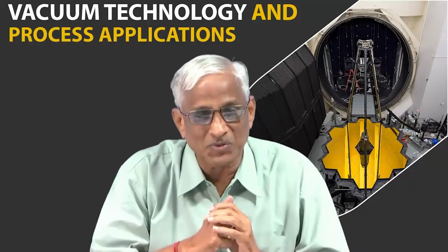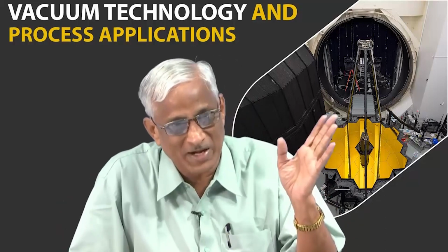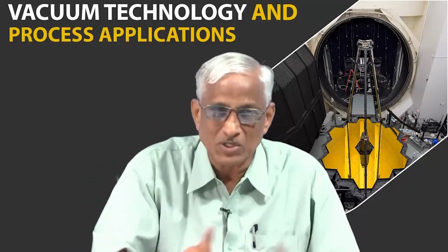So, what you should do is immediately run the air blast for some time. The air blast operation we have explained in the rotary pump class. If you want, you can go back to that class and understand. And again close it. During this process, if the vacuum is improving, then you are going in the right direction.